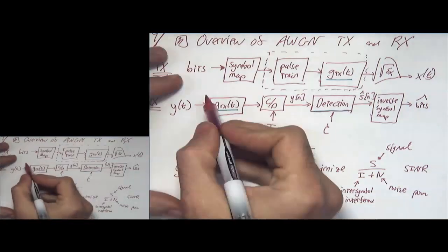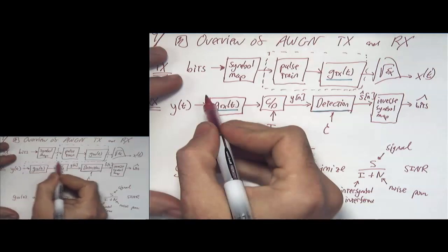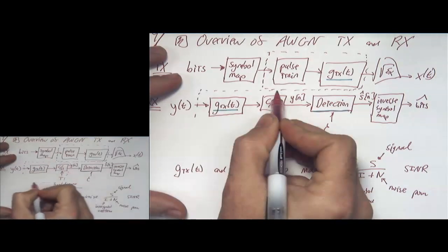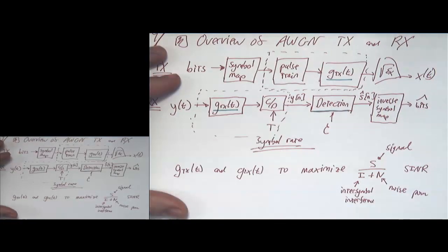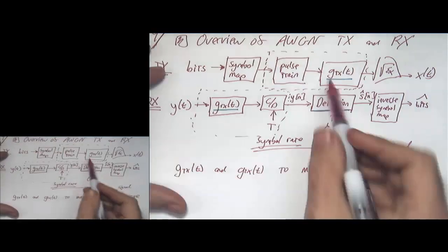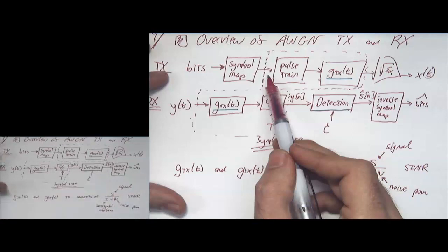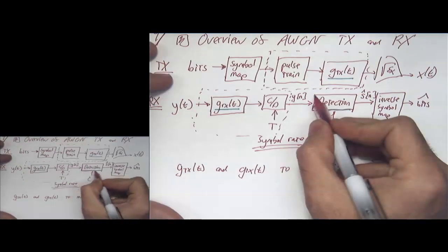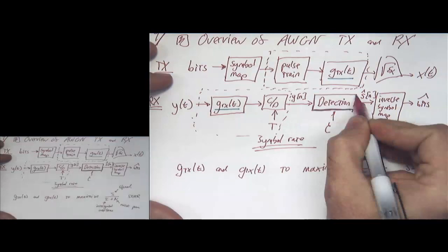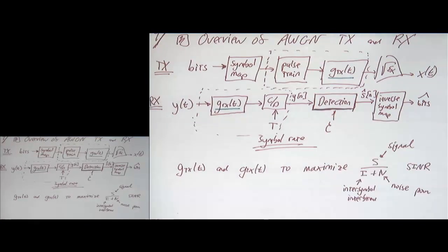And then similarly, at the receiver, we're going to replace this set of functions here with a continuous to discrete converter operating at the Nyquist rate, followed by digital filtering, followed by subsampling. So we're going to use some tricks from multirate signal processing to essentially enable us to convert these into digital functions. So that's what we're going to do Wednesday. And then the following week, we will derive the ingredients of the optimum detector here. So that is it.